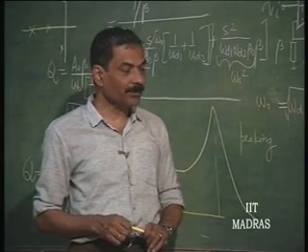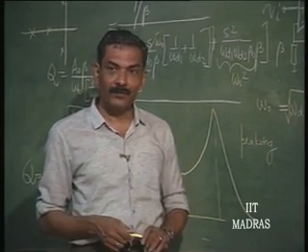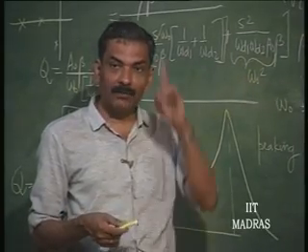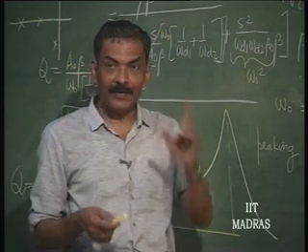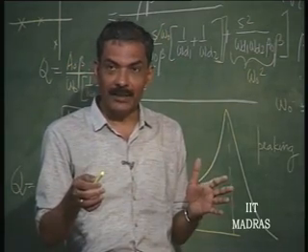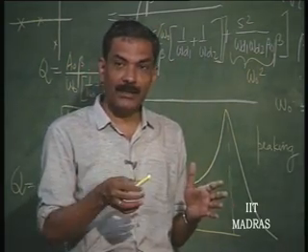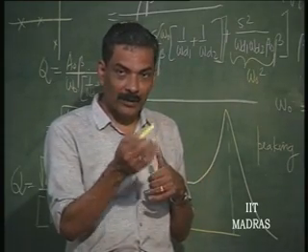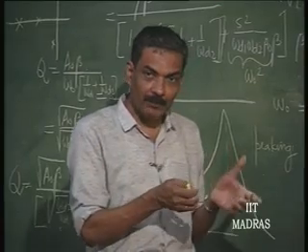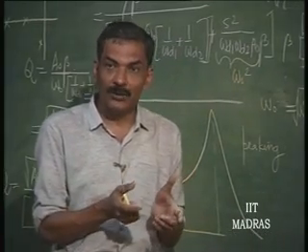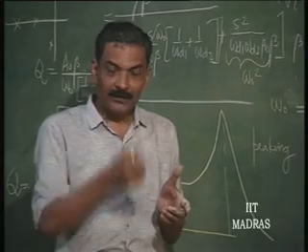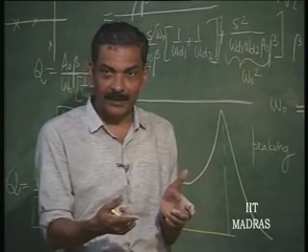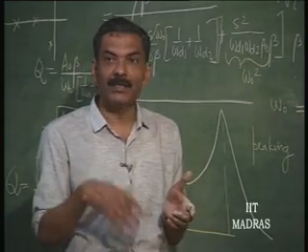That is primarily coming about because of the frequency dependence of the amplifier. Another way of interpreting this is the loop gain becomes equal to 1 in magnitude when the phase shift of the loop gain becomes equal to 180 degrees. What is negative feedback? The output is developed in a manner that the input voltage and the feedback voltage are opposing one another. Now, because of frequency dependence, if the loop gain has an additional phase shift of 180 degrees, what is considered negative feedback becomes positive feedback.